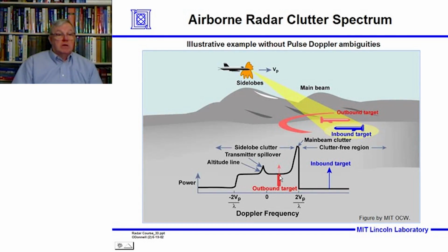And here we see the target competing with the side lobe clutter, which could very well be a significant issue to deal with. So the main point in just these three view graphs I want to put out is that airborne clutter rejection is a lot more complicated and deserves a couple of lectures all by itself. But I just want to point out to you some of the issues as to how ground-based radars are different and what they have to do than airborne radars, and what some of the differences are in a very general sense, because this is an introductory lecture.